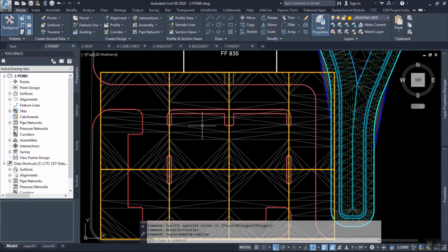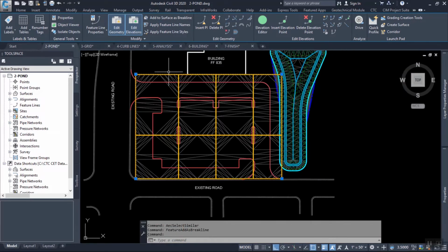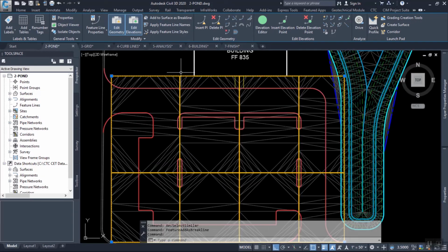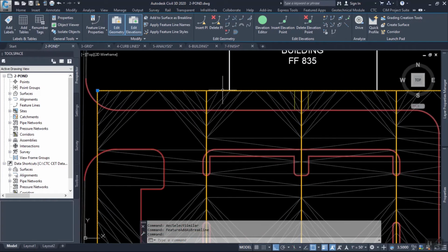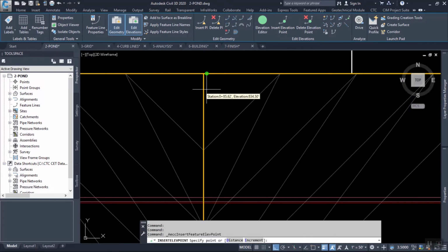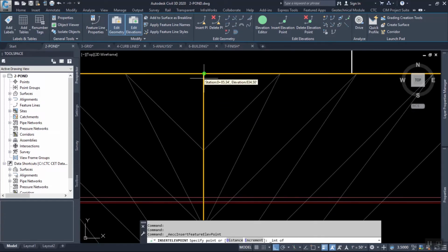We're going to add or put these on a different surface, a parking lot setup surface. Same supplementing factors, okay. Now what I want to do is start to define sheet drainage regions within my site, okay. And what's really handy for this is to create feature line labels that label the spot elevations and the slopes on them. But the other thing we've got to do is put some more vertices in here. So I'm going to do a little bit of this, and then we're going to jump forward to the pre-baked next drawing.